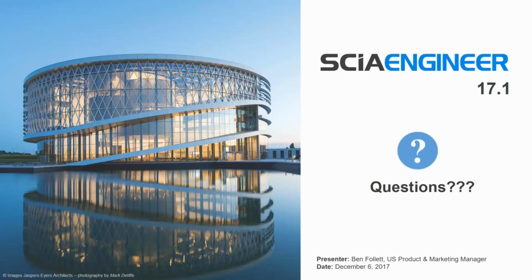And so that's a nonlinear option in the software. When you're using that functionality, you don't have the need for notional loads, because notional loads are really just used to apply them at the top of a member and give you that out of plumbness and out of straightness. So there's a way to do that without needing notional loads at all.